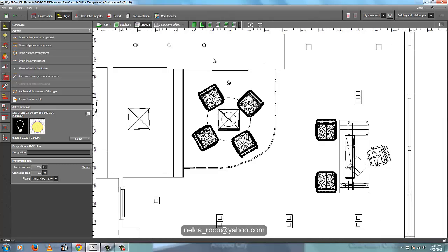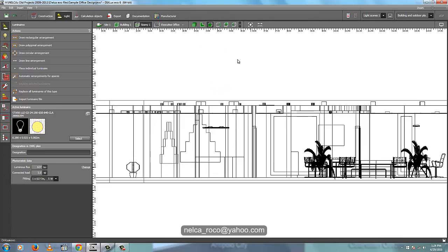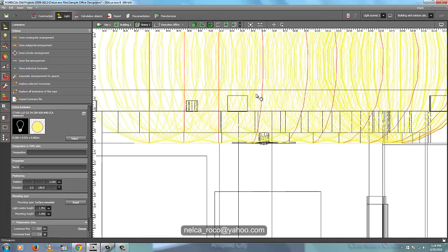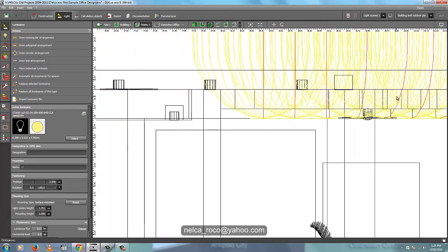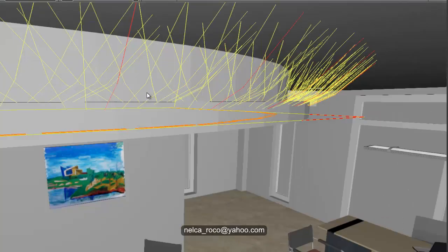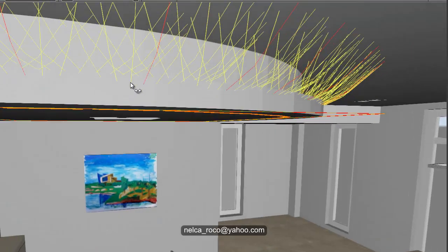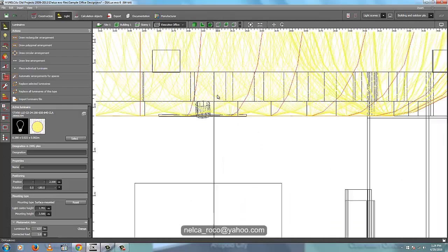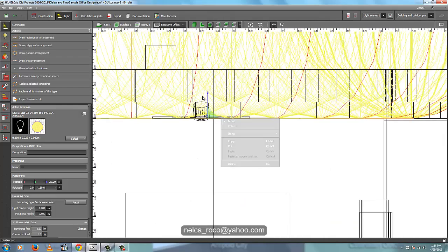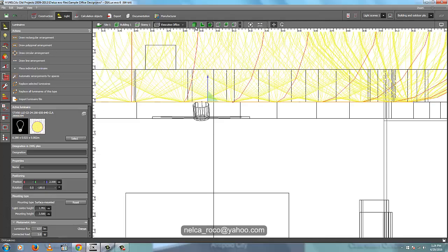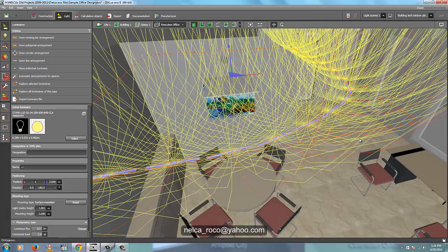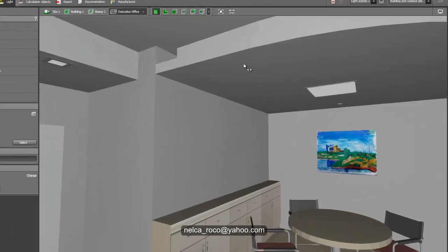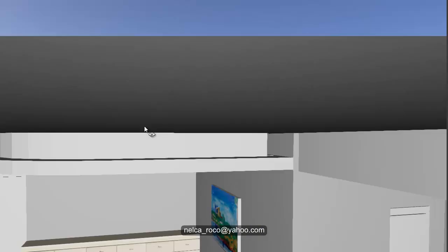First the executive, and then elevation, and then select these lights. Is it properly placed? I think it is not. See, it is not, so we need to move it up. Then right click and move. Here, this is the right one. So I think this is fine. Now you have the LED strip on the curve.